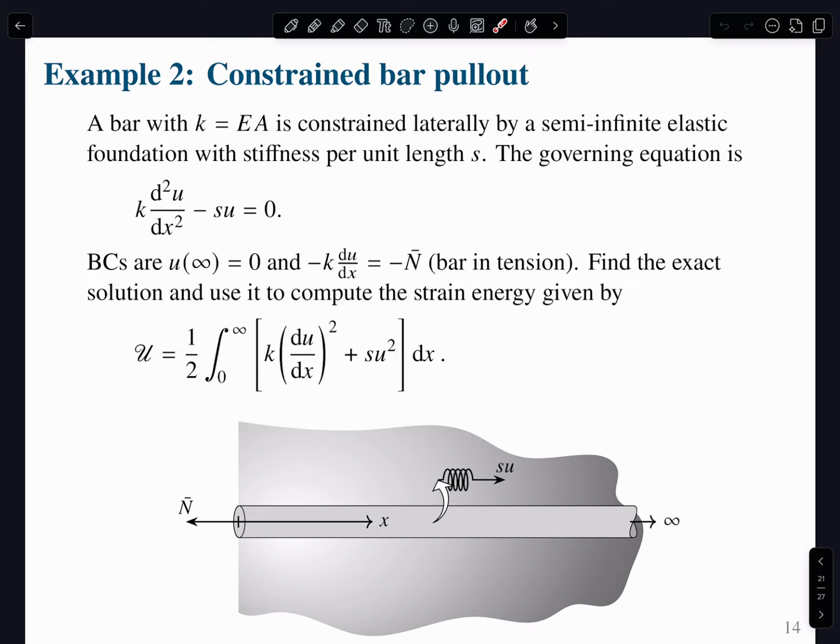And then I'm really trying to pull the bar. So boundary conditions are, well, I have applied a force. I'm trying to pull out this bar to the left, right? And that is basically my Neumann boundary condition. Then remember that there is a minus sign here, because why is that minus sign there? Yeah, n is minus 1. That's why we have a minus here.